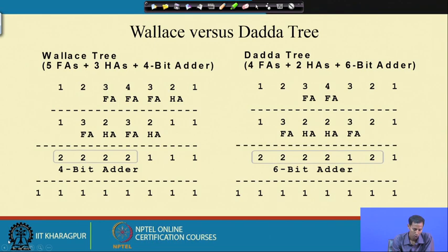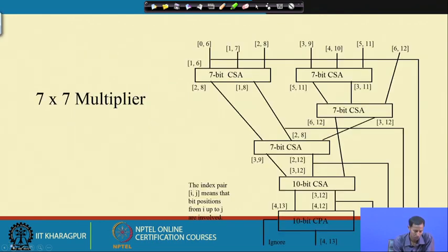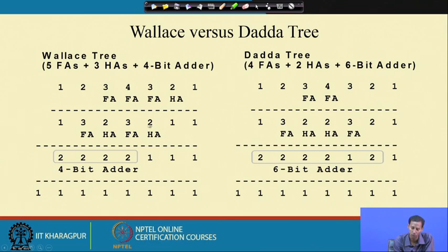Okay. Then after that I have to use one half adder for this 2, full adder for this 3, half adder for this 2, full adder for this 3. Once again I consume this half adder for this. So, this will produce 1, this 3 produces 1 and carry from this. So, it requires 2.